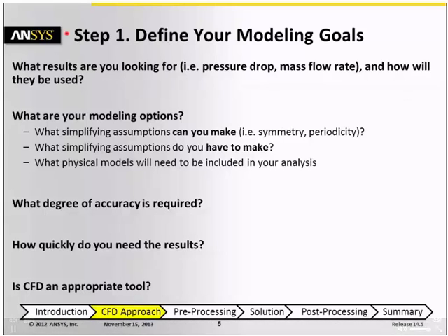In any CFD project, the very first step should be to define the goals. It's very important to know what information you hope to gain by doing the simulation. For instance, maybe it's the pressure drop or the mass flow rate, and also how the information will be used.